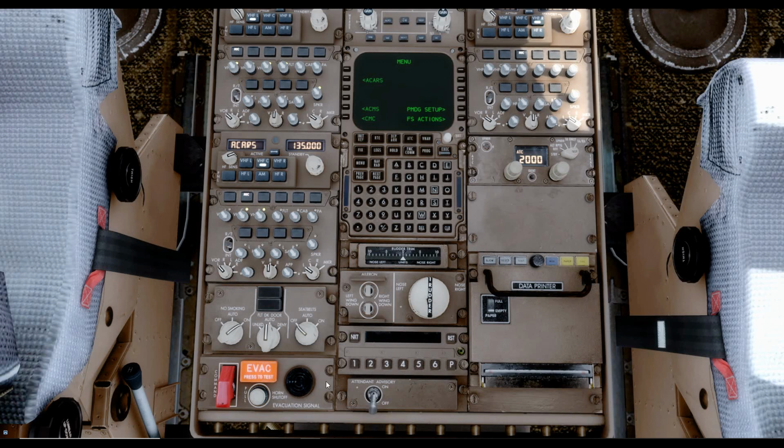So we'd get on the PA, tell them we were going to do it, press the evacuation command, the horn sounds, the light flashes, and the horn shuts off, turns off the aural warning. We then place the guard back on the switch, and the cabin crew will speak to us on the interphone eventually and say that the test was successful.